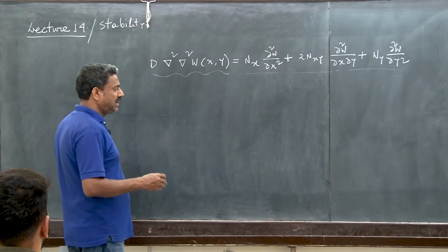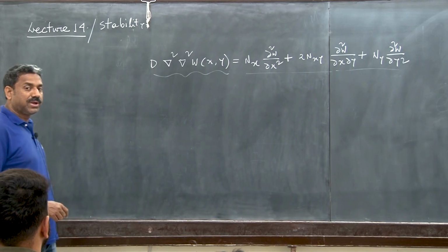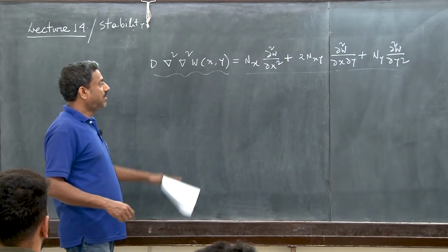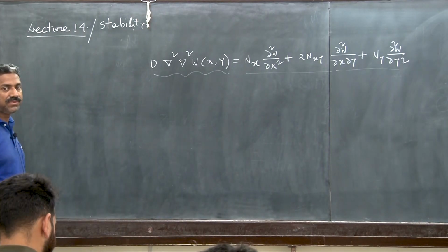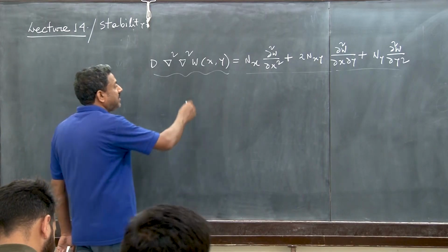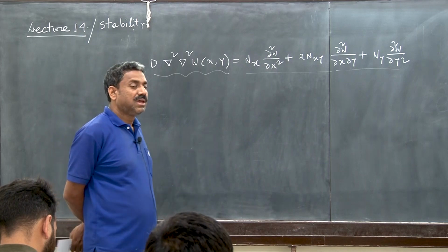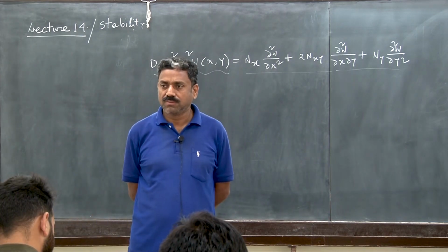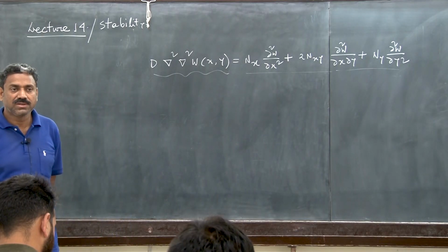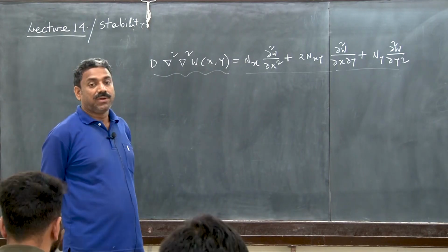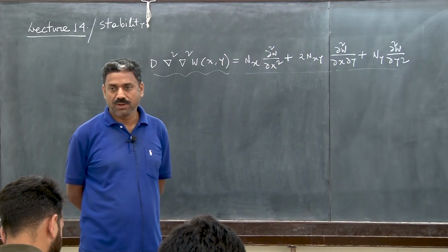Now, then we have considered a simple example to solve. We have considered a simply supported plate, which is subjected to uniaxial compressive forces, and then we solved it, and we have seen that this results in an eigenvalue problem as earlier. We have solved the trigonometric eigenvalue problem. We assume some double Fourier series involving sine functions, and by satisfying the boundary conditions, and the boundary conditions for the simply supported plate we have